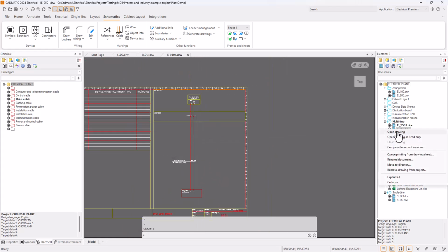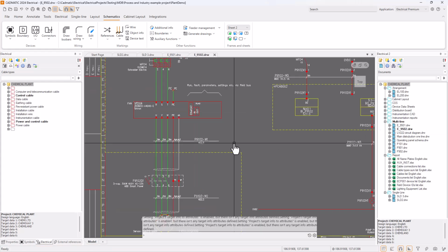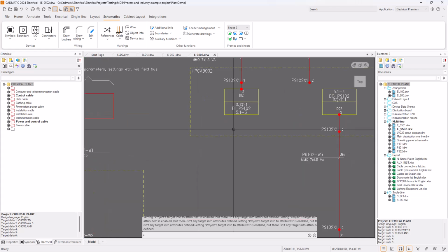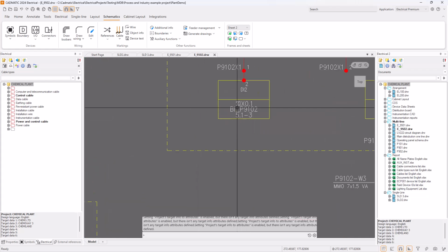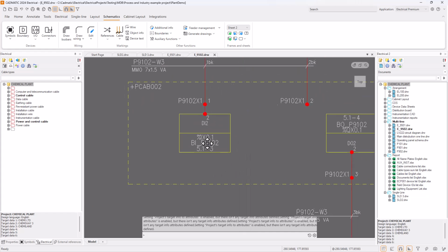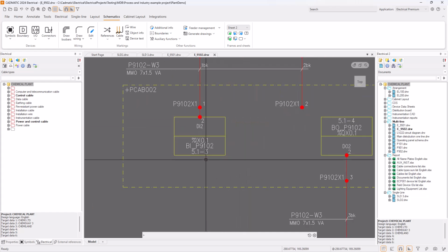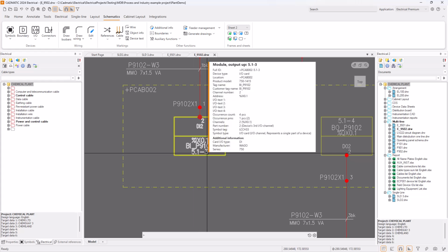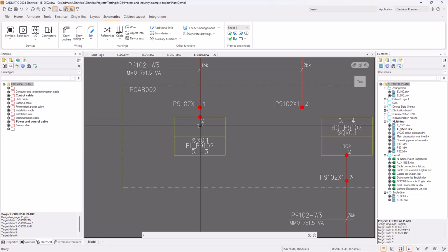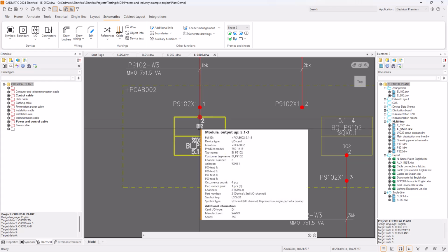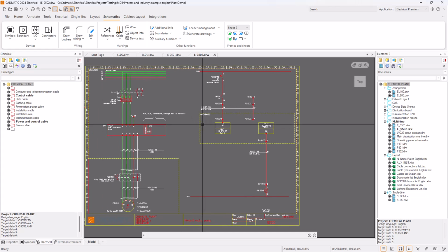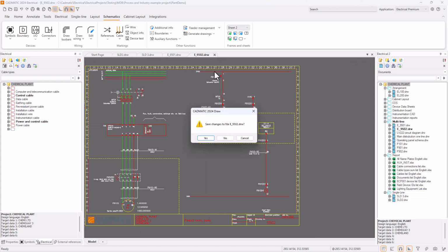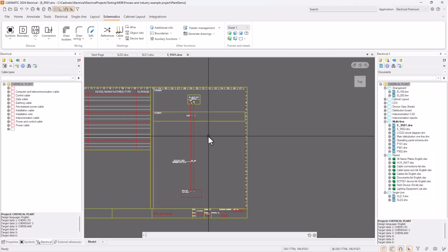If I now also open those frequency converter diagrams, you probably saw that when opening the document, the information was added into the symbols. So which rack, which card, what the channel is, what the channel pin number and description for this pin are, and so on and so on. So everything is now updated into your circuit diagram also, just by drag and dropping IO points to the channels in the database tool.